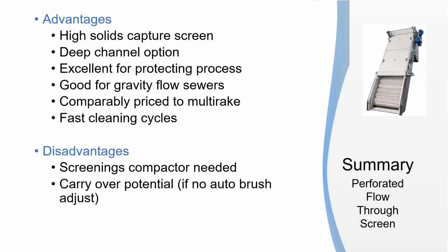It's also very good for gravity sewers because of the way it's designed with the strong panels. A lot of these screens are good at handling gravity sewers. They can take a bowling ball coming down, they can take logs and stuff coming down. So some of these I may not be able to remove, but at least it's not going to be landing on top of it like a center flow would.